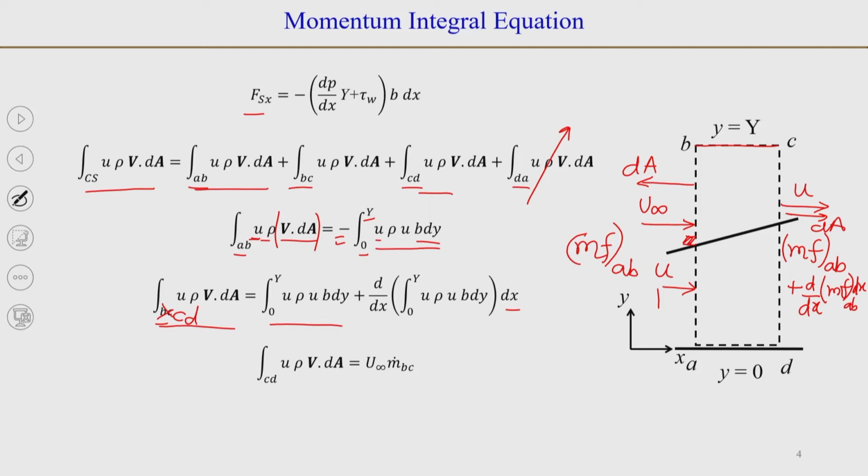So, the flow which is going from here to here, there is some change in the flow rate, because when you consider, say, a boundary layer, at the leading edge the velocity is uniform, but when you go inside the boundary layer or somewhere in the plate region, then there is a velocity gradient. So, the flow has to divert in this region.